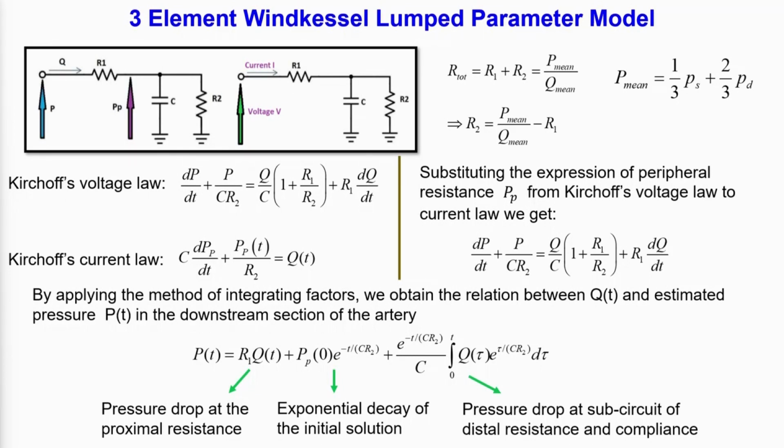So, the sum of these in the right hand side is the total voltage drop, if you are traversing the path, the charges flowing along R1, then the charges being stored at C. And similarly in the left side, the same voltage is the sum of these, dp dt, where you have the first node, and then if you imagine the flow path through R2, that is P by C R2.